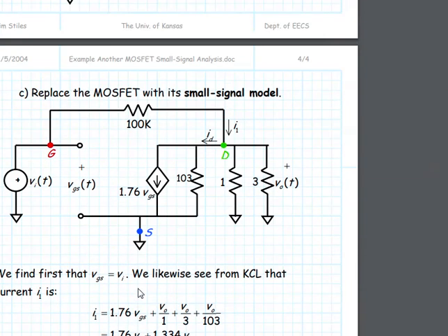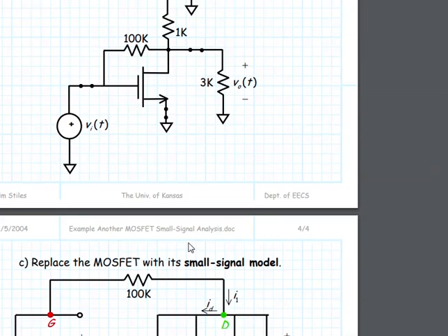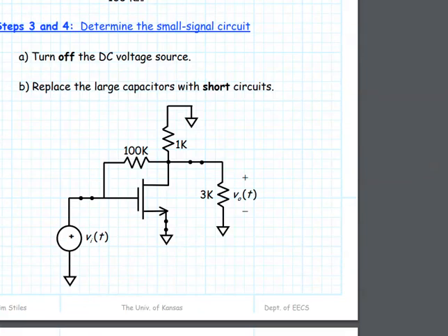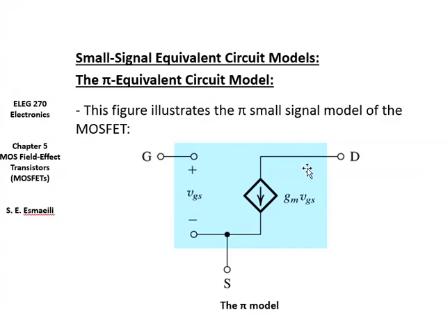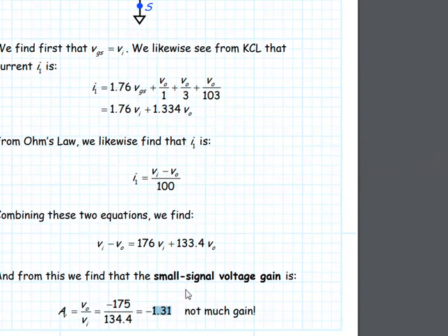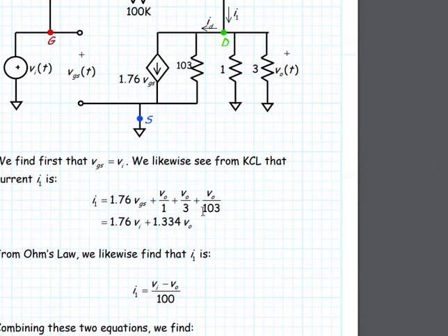But now I have an exercise for you. Redo this AC analysis, because now we did it together. Just this time, remove this 103. Just use the model that we use, this model. Don't use the RO. And I want you to see how close the answer is to this one. This way you will make sure that it's not a big deal to remove this RO.